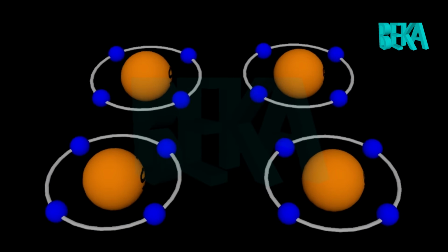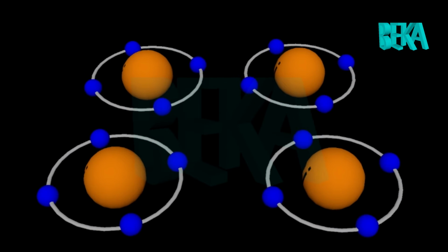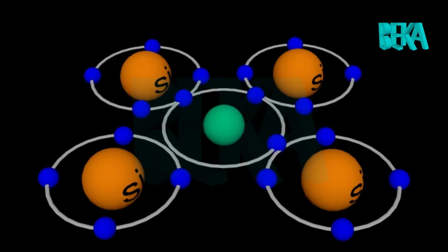When pure silicon is doped with a trivalent impurity, the 3 valence electrons of the impurity bond with 3 of the 4 valence electrons of the silicon. This leaves a hole in the impurity. These impurity atoms, which are ready to accept bonded electrons, are called acceptors. With the increase in the number of impurities, holes are increased. Hence, it is called a P-type semiconductor.